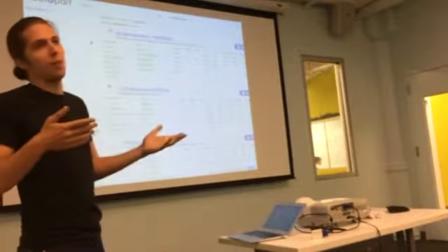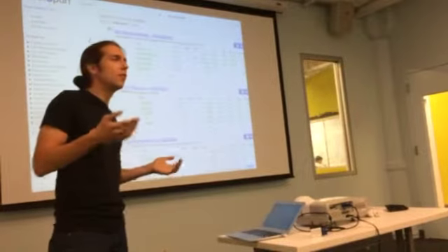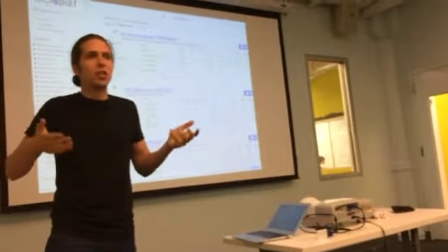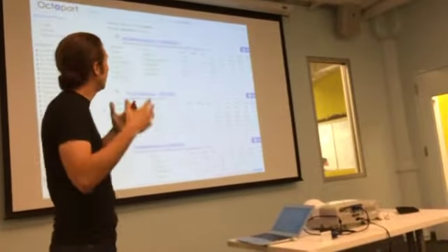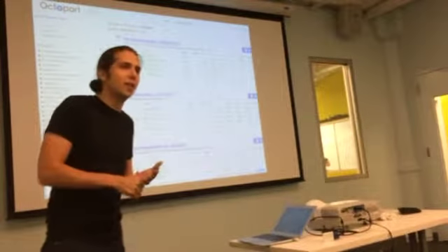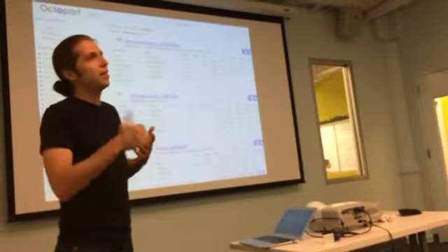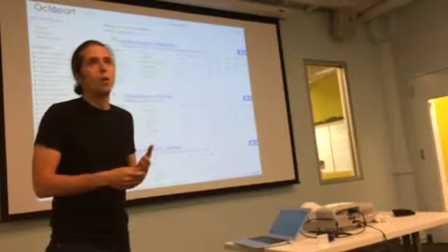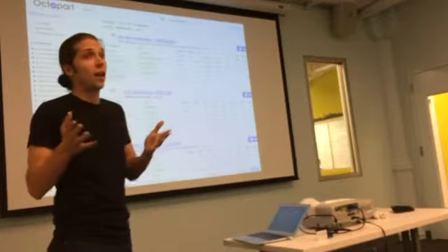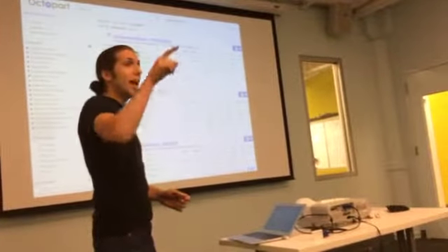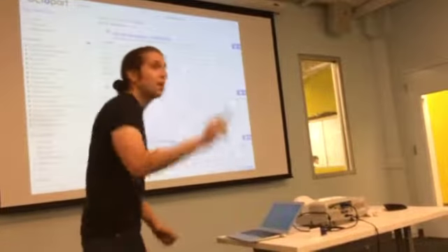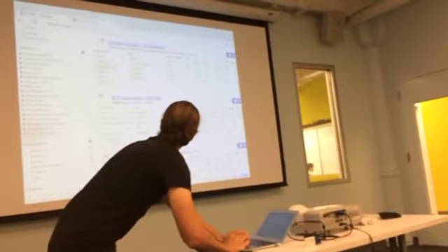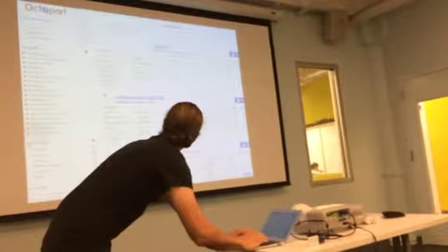But let's say you don't know the part number of the thing you're looking for. Let's say you're looking for a capacitor. Has anybody here been looking for capacitors for their projects? Yeah, it's something you've got to do from time to time. Let's say I want to find a 1 microfarad capacitor, and I want it to be tantalum surface mount in an 0603 package, up to 20 volts. Let me show you how to do that. X7R? You got it. So not tantalum. That's a ceramic multilayer X7R. Okay, we can do that too. So let's type in capacitor.